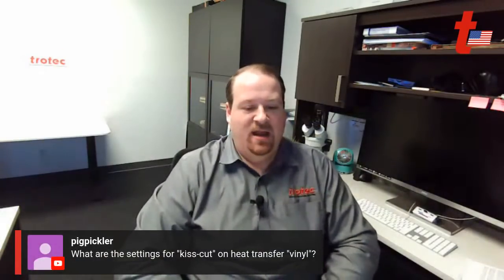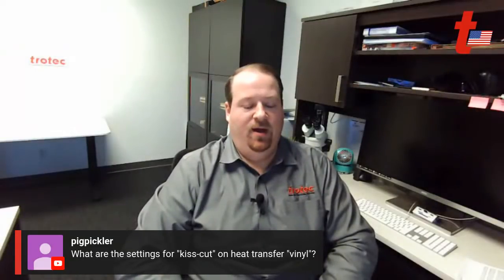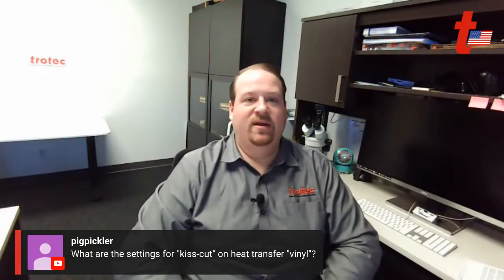Next question. What are the settings for kiss cut on heat transfer vinyl? That is going to be kind of a difficult one because it depends on your laser, your wattage, your type. Contact us specifically and I can give you some guidelines on that. But I would suggest just doing a little bit of trial and error. Just cut a little box and then throttle your power back, running at the same speed, and keep throttling your power back until you get a nice clean kiss cut, and there's your setting. That's how I would dial it in.